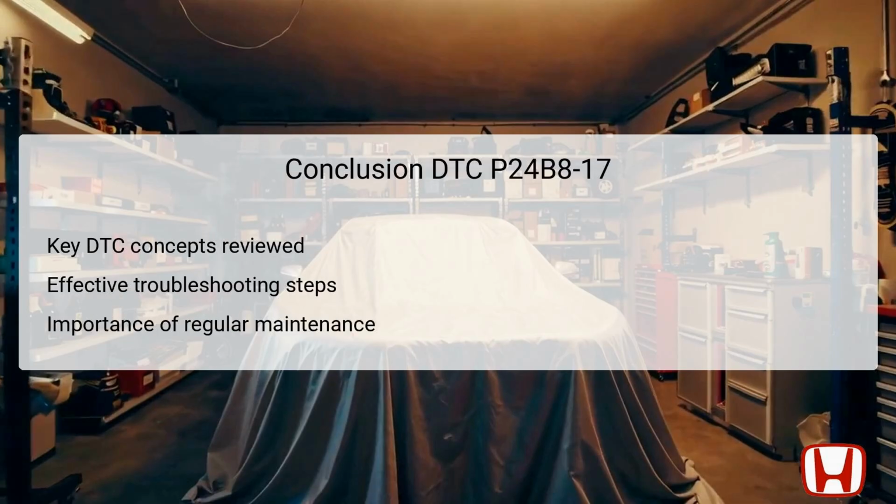In conclusion, we have reviewed the important aspects of DTC P24B8-17 and its implications for the Honda CR-V 2023 and newer models. Understanding the error code, its causes, symptoms, and effective troubleshooting steps is vital for accurate diagnostics and repairs. The effective inspection of related components, including the ELCM pressure sensor and wiring, is crucial for resolving the issue efficiently.